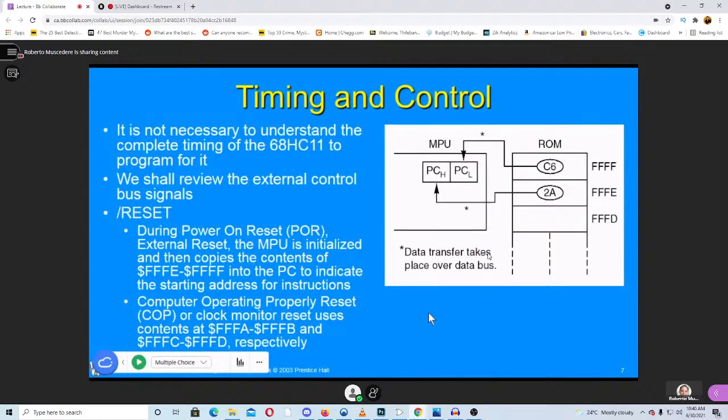I've seen a number of devices over my time where normally you see a device and it has a light that tells you it's on. But does that mean it's working, right? I've seen other devices where they have a light telling you there's power on, and then there's a flashing light. If the light is flashing, it means it's working, because the software is actually flashing the light. If the software isn't working correctly, it would never get to the code that flashes the light, and you wouldn't see the light flashing, and that would be some indication that something is wrong. So just by looking at the device, you say, why isn't the light flashing? Then you know something's wrong. It's kind of like that type of thing.